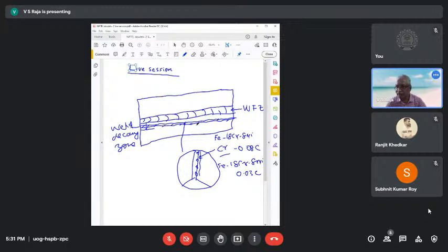Let me now go to the next point. The question reads like this: I experienced an A106 CS pipe welded with ER70S3. After 1 year of service, the weld area corroded from inside. Almost 70% of the weld metal is gone and now looks like a groove. Is it galvanic corrosion? What would be the cause? We expect untreated seawater is passed through the line, even though why exactly is only the weld metal washed? So this is the question.